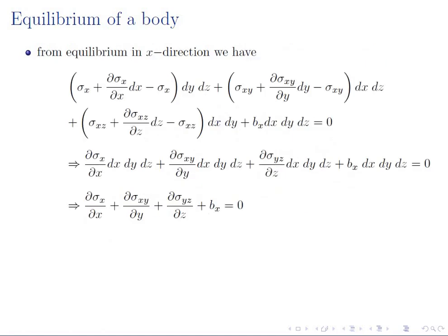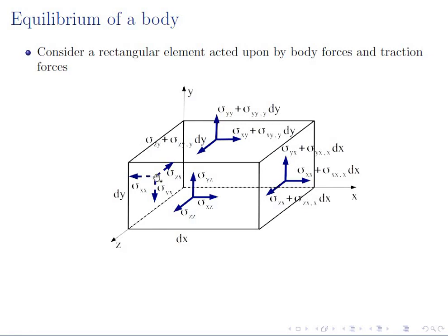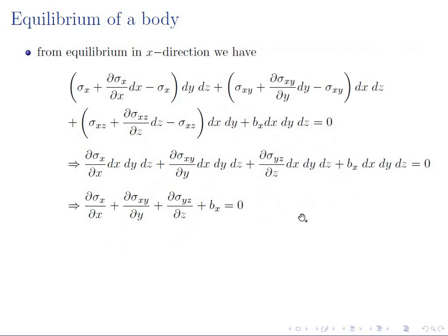Let's look into the equilibrium of forces in the x direction. Sum up all the horizontal forces, so the force created by sigma xx and the force created by sigma xx plus sigma xx comma x dx, and multiply it with the corresponding areas.